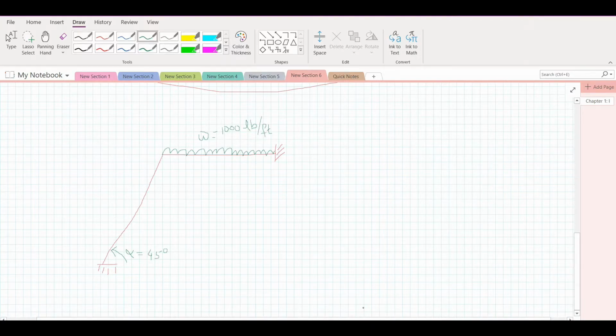The reason why I'm doing some problems in metric systems and some problems in the US customary system is that I want to show that ABAQUS is a generalized program where the response depends upon the units that you specify. If you make an error in specifying certain units, then you will obtain wrong results, or results that are not in standard units. Therefore, we need to be very careful assigning the units in ABAQUS.